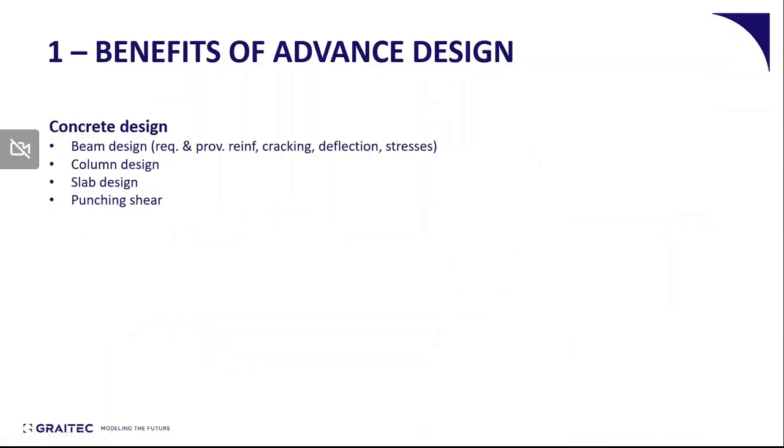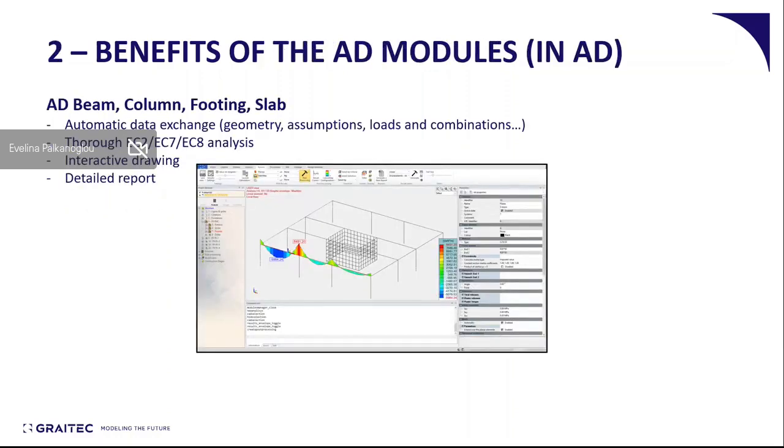The concrete design offers a wide variety of modules for different structural elements: the beam, the column, the footing, and the slab. We deal with cracking and punching here as well, quite effectively. As I mentioned before, the modules are very effective as well, and cracking is taken into consideration, as well as the total deflections of the concrete, easily.